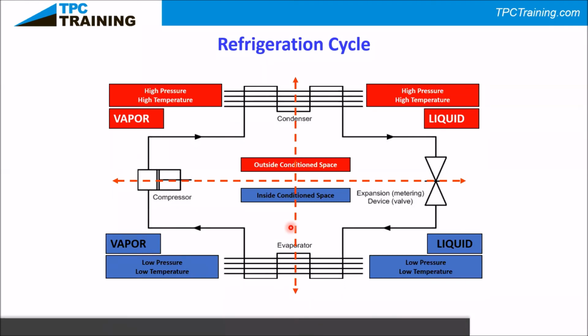Question here about the heat pumps. Does a heat pump have an evaporator? I would presume that it would, just on the outside, right? Well, a heat pump has both. The same as what we're looking at here. I'll lift the screen up here. It's just taking this condenser and flipping it inside and outside. So what's happening with a heat pump is they work as both the evaporator and the condenser. The inside and outside coil can be the evaporator at any given time or the condenser at any given time. So it just kind of flips the refrigeration cycle.